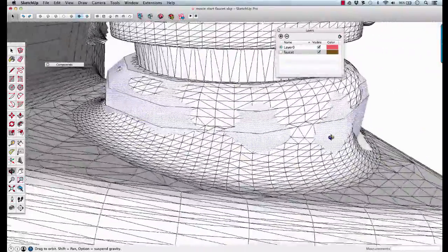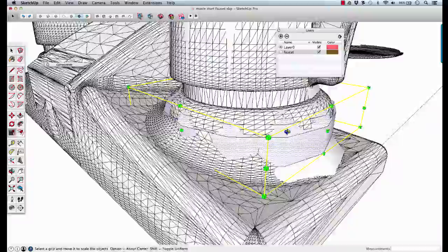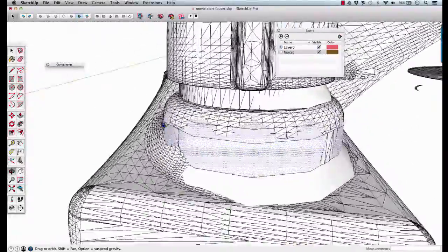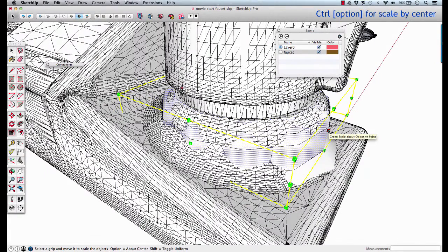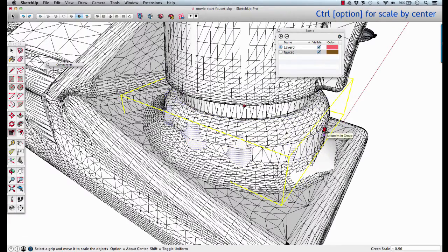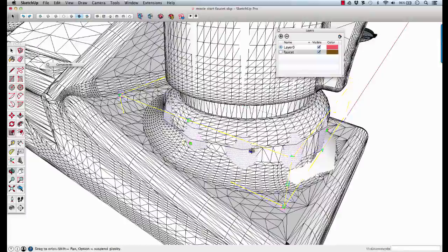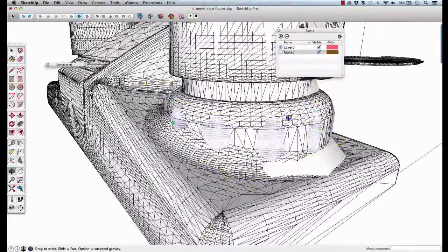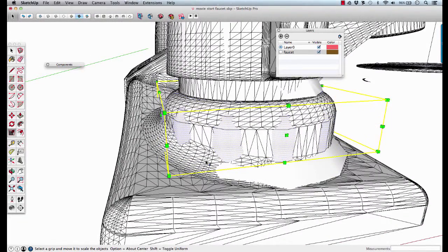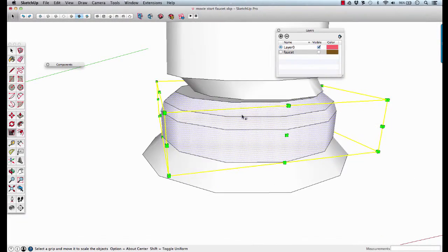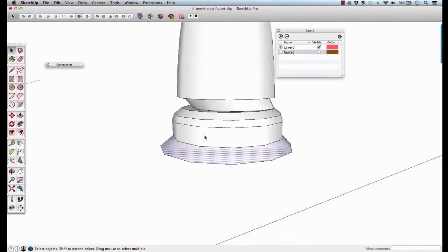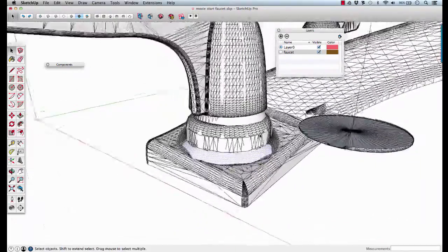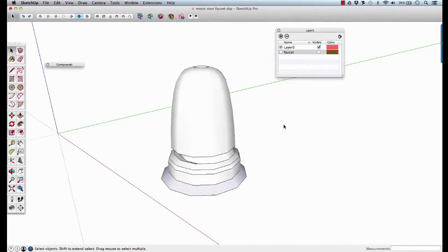So we've brought that in and it's smushed that into kind of an oval shape. Now this side part got adjusted because of that scale, so we'll go to the side grip, and here we will go about the center. Click, push-pull that inwards. There we go. So we've now matched our CAD. The last thing is this sloping area at the bottom. This gets a little harder to do because you actually need to move these things upwards, but we'll leave that for later. So now there's our faucet handle base.